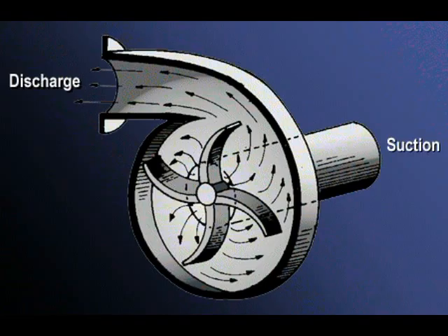One type of pump commonly used in this part of the plant is a specially designed centrifugal pump that has large openings that allow solid objects and stringy materials to pass through the pump without damaging or clogging it. This type of pump is called a non-clog centrifugal pump.